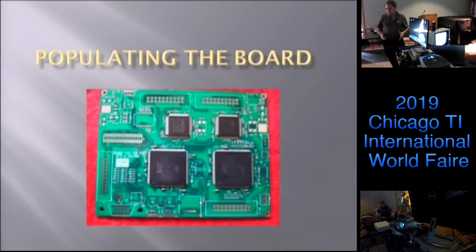So in this case, if you're hand soldering the board, the chips are rather large and the silicon is actually quite small in the center of the part. So the heat that you're putting on the pins is, I mean, you still have to follow good practices and not keep the heat on the pin for a long period of time, but you can actually get by with hand soldering this board.